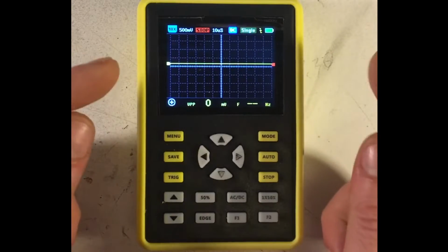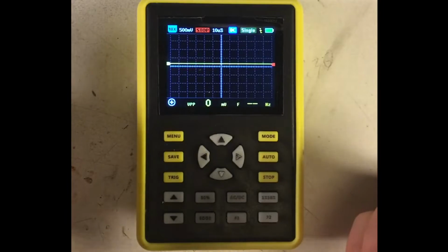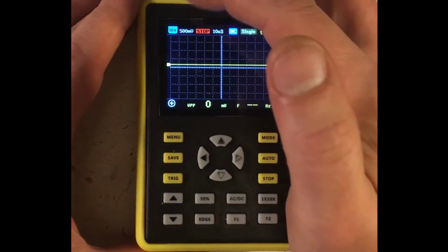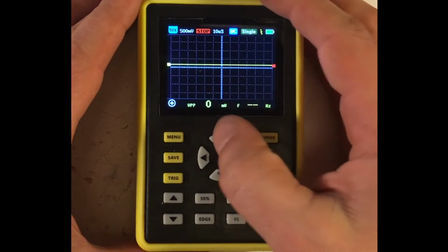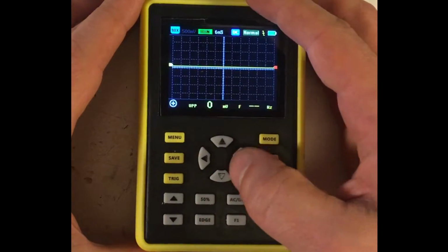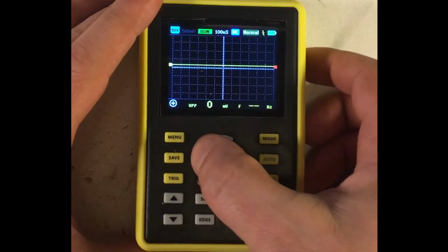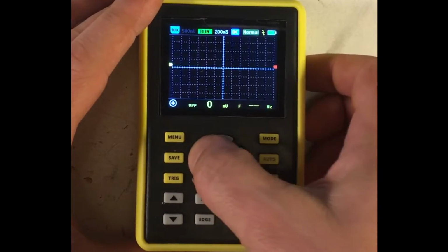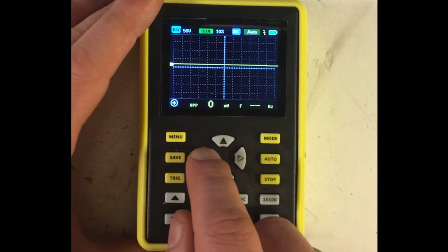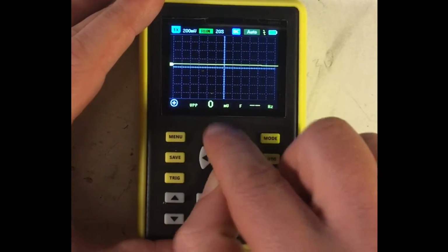Now, I do suspect some of that comes down to the hardware and how they have the ADC clocked and when it's taking in samples and when it isn't, because also built into the firmware, you change your sample resolution or your sampling speed depending on some of these other measurements. So when you're in the very low time bases here, and this can go down all the way to 6, which is very nice, and you can go all the way up to, I think, 60 seconds or so, which puts you into slow mode, which is also very nice. We have additional times available to us. This is slow scroll mode, so it goes all the way up to 50 seconds-ish, which is nice, but a little bit weird that they lock you out of some of this stuff in the other modes.